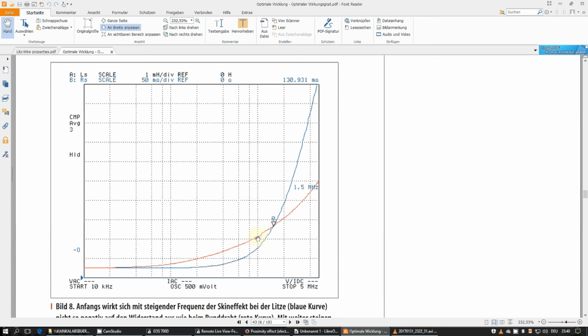with a minimized proximity effect. For example, if you use a relatively thick wire and you place the turns with a great distance to each other, it could be better, even for AM radio, to use single wire than to use much more expensive litz-wire. So at the long wave range, it's clear litz-wire has a great advantage. At medium wave, it just depends.